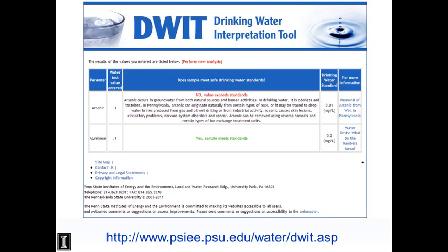And so I typed in arsenic at 0.1 parts per million, which is 100 parts per billion, and it says it doesn't meet the acceptable standard. Now that's the public health standard for a community water supply, but it's really the guide, the MCLs that we mentioned before, and the drinking water standards that are used for community water supplies is really what you should use for your own drinking water supply. That's where EPA has deemed the level of any kind of constituent is safe or not, so to speak.